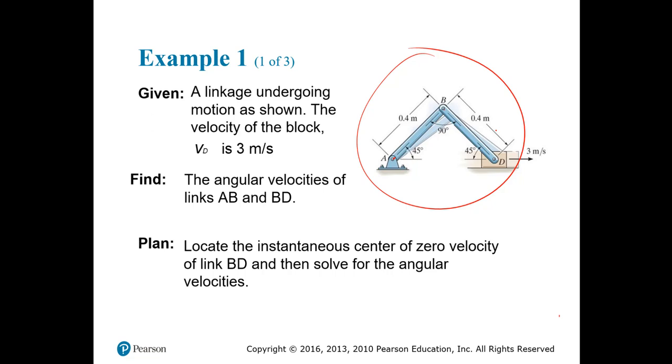So why is this so important? Well, guys, like I said, we need to isolate everything into one single element so we can work it in a better way. So if you see A, B is rotated with this, you can see here the probable movement. So if that's the case, you already know that it's moving with a circular pattern and therefore the velocity in B will have this direction.